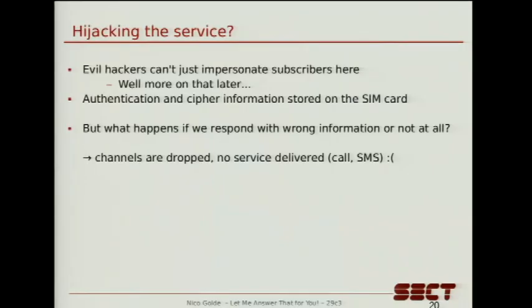So the interesting part here is obviously what stops a subscriber from just responding to paging requests which are directed to other phones. Can't we just use this to hijack, for example, a service? In reality, this is not so easy, because the authentication and ciphering step that I mentioned is based on a secret which is stored on the SIM card. What actually happens in practice is the network sends a random challenge to the phone, which is combined with the secret key on the SIM card and produces a response which is sent to the network, so the network can verify whether the subscriber is really authenticated. This also forms the basis for the encryption which comes later.